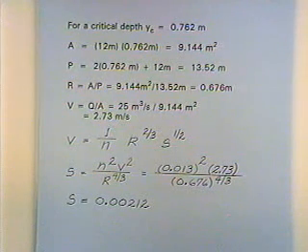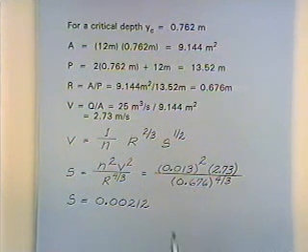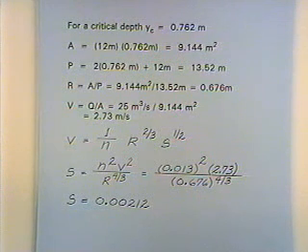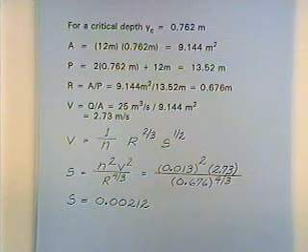And so the actual depth, we're assuming uniform flow, that there are no other irregularities. It's an otherwise prismatic channel, and so we'll use Manning's equation. And so what we've done, and again we could compute the depth upstream and downstream. What I've chosen to do just because I'm lazy and I could eliminate one computation, instead of computing a depth upstream and a depth downstream, that's two numbers, I'm just computing one slope.